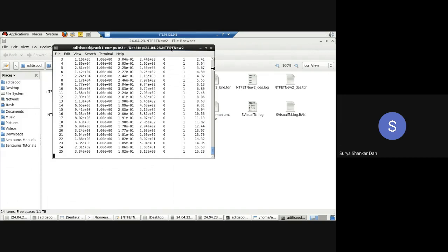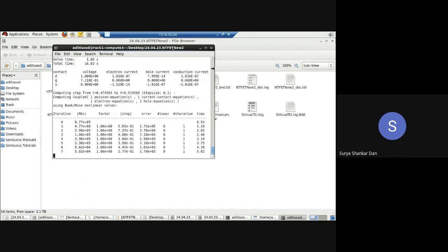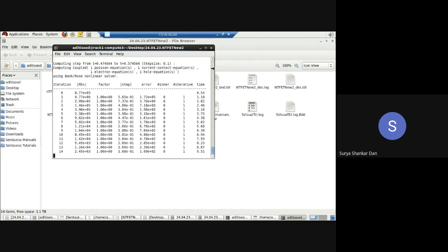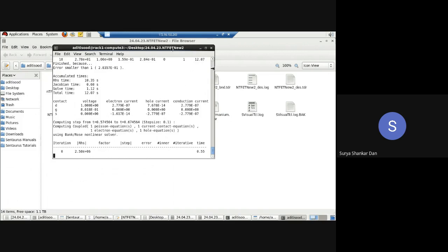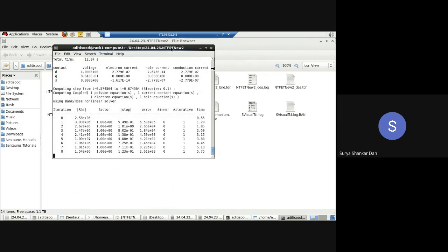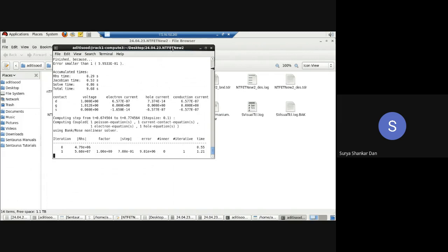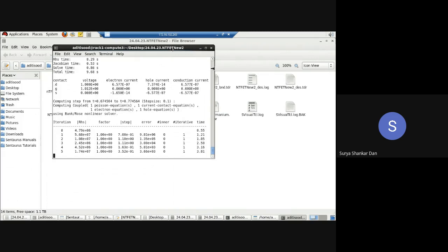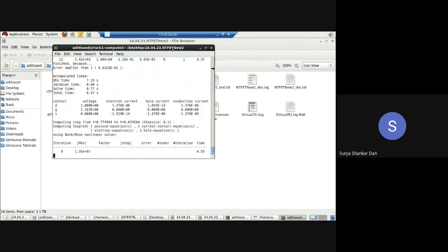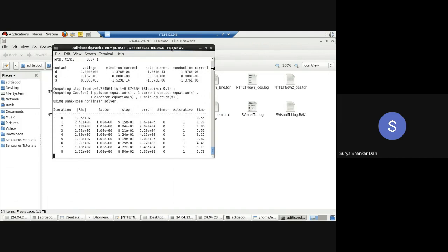If you are really interested, Newton-Raphson is essentially the fastest one, but the most inaccurate one. Newton-Raphson gives you first-hand results on how the device will work and how the circuits will work in the case of Cadence. But it is definitely not the most accurate one. So what is more accurate than that? There are several techniques of carrying out the numerical methods. One solution is Newton-Raphson, as I'm telling you what is happening over here.